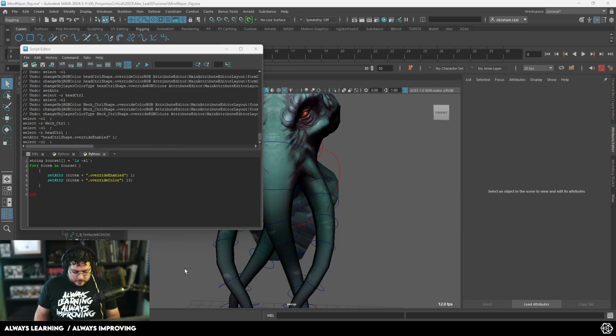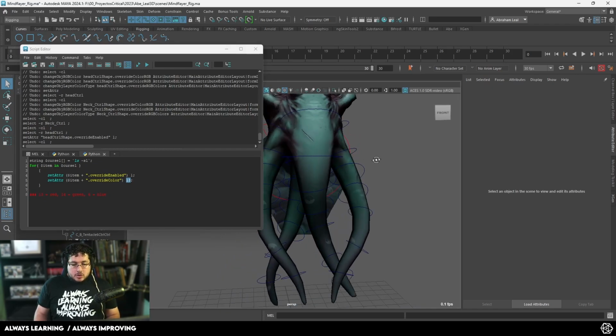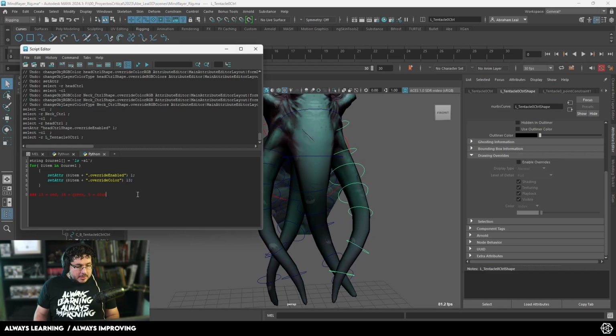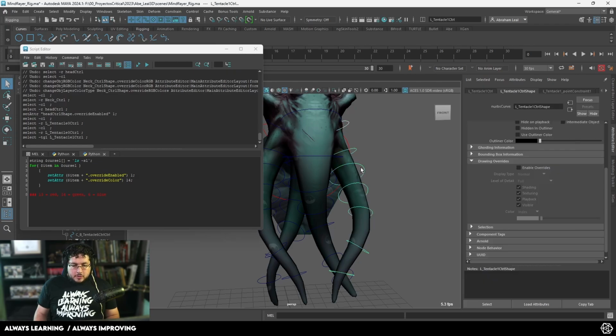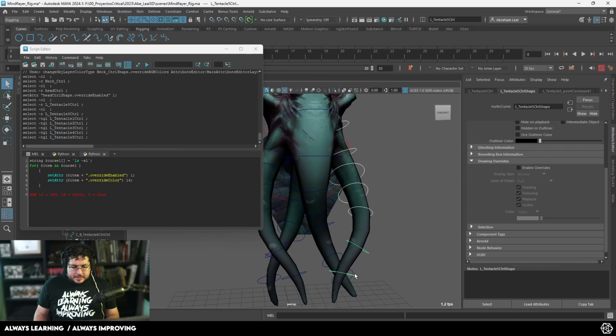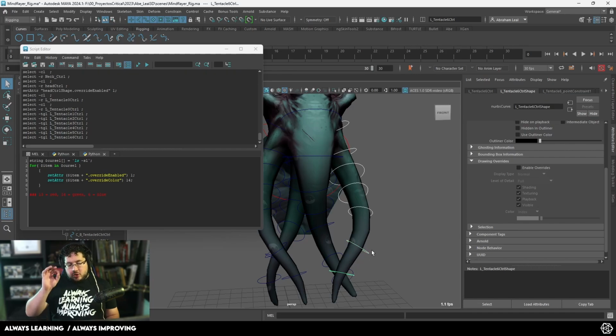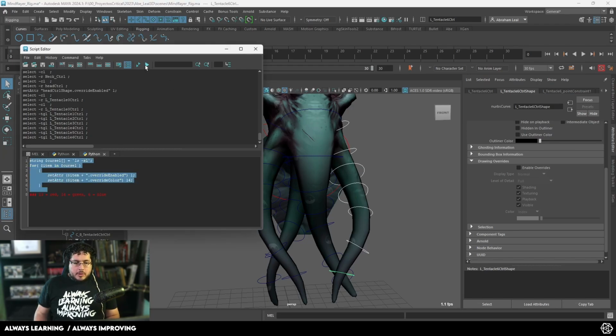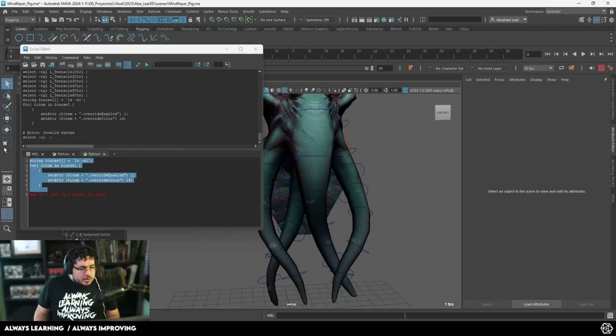There you go. The number on the index is the number that you're going to be replacing. As you can see, the number 13 right here is going to paint all of my curves red. If I wanted to paint all of the left ones green, I'm going to change this value to 14. So I'm going to select all of the curves right here. What this script does is exactly the same thing that I was just showing you, but you cannot select all of the curves at the same time, so this just makes it a little bit easier. Just grab all of this, run this, and there's an invalid syntax.